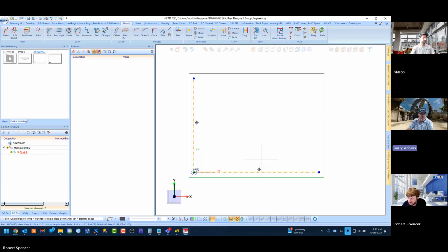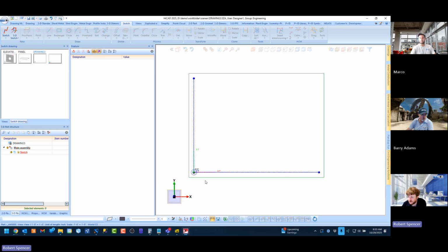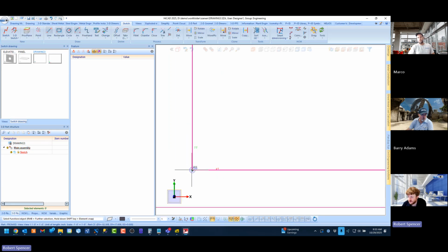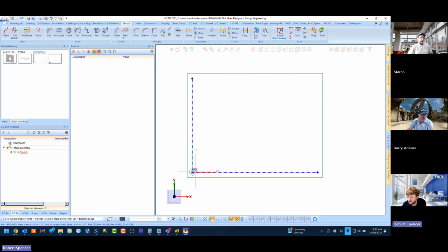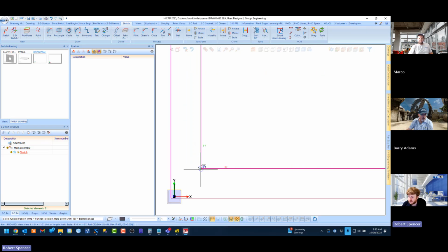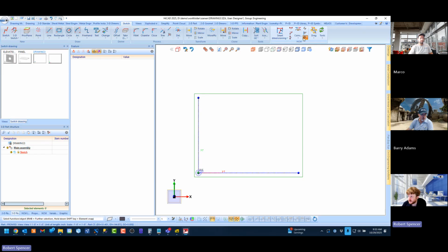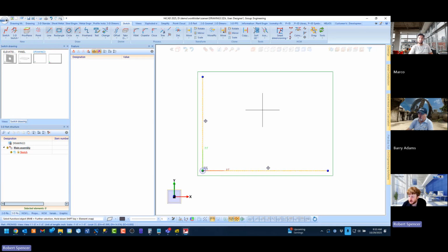You're making it coincident, which is right. Basically, I'm affixing, just taking these lines. This is coincident to origin just because I snapped to it initially. But this doesn't matter so much really because we're just gonna click this and say fix. And now these lines are basically glued to the current location in a way.